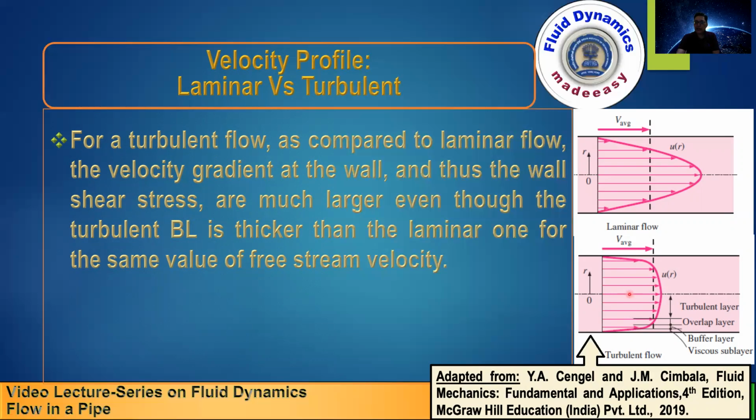So this fluctuating transverse velocity, the fluctuating V velocity, causes a fluid particle to move from a particular layer to a layer above or below. So if you consider, let us suppose, this layer, and a fluid particle moves to an upper layer, which is moving at a larger velocity, then it tries to reduce the velocity of the upper layer. If it moves to a lower layer, then it tries to increase the velocity of the lower layer because the lower layer is moving with a smaller velocity.